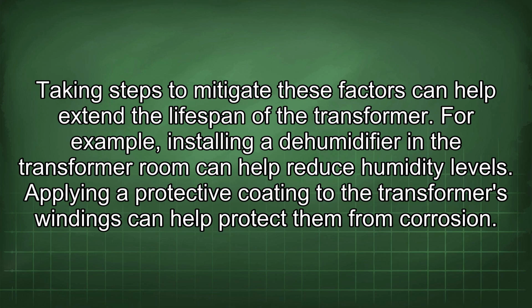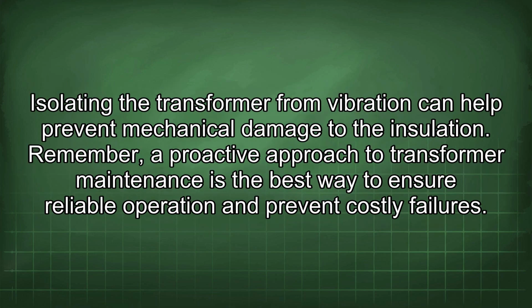For example, installing a dehumidifier in the transformer room can help reduce humidity levels. Applying a protective coating to the transformer's windings can help protect them from corrosion. Isolating the transformer from vibration can help prevent mechanical damage to the insulation.